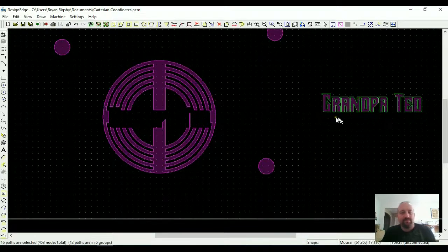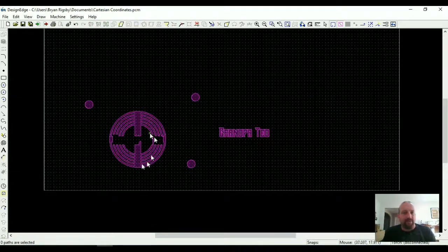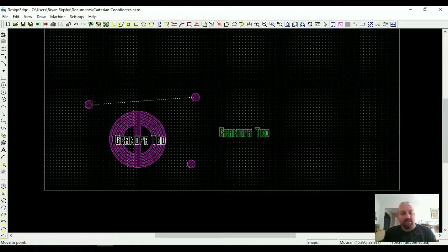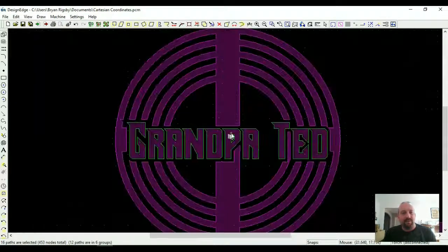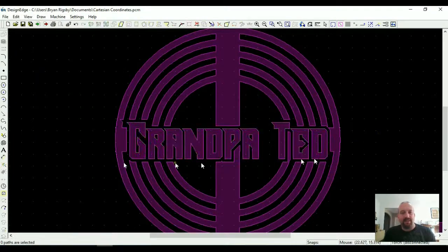So now let me put my text in the middle of my circle and see what we get. So I'm going to select the text. I'm going to hit M. Again, it's going to ask me move from. So I'm going to use my same reference point. I've kept the circle with the text. Anytime I've moved anything around, I've kept a circle either by copying it or moving it. So I'm going to move from C center snap of this circle to the C center snap of this circle, and it'll pop my text right in there.